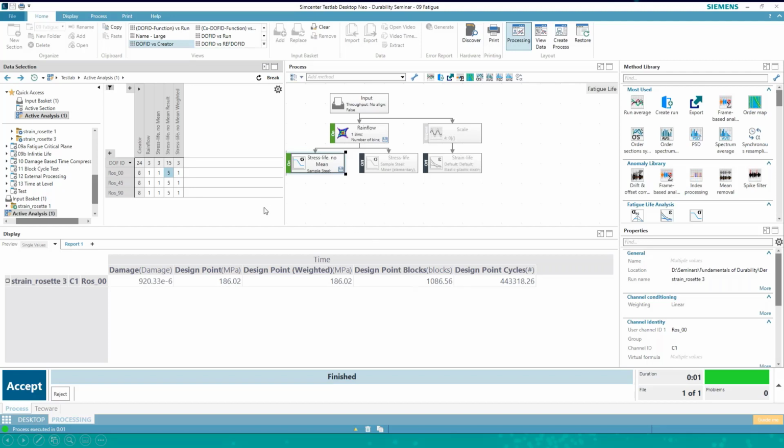If I click on all these, now it says that my 0. But here's why I always caution you about using one strain gauge. If I would have just put one strain gauge and I'd have put it at 90, look at the difference. So obviously the lower the number, the more damaging the direction of the gauge is. So a gauge, if you rotate it, can get significantly different max damages. So typically we resolve this every 10 degrees, calculate the damage, and take the max one.